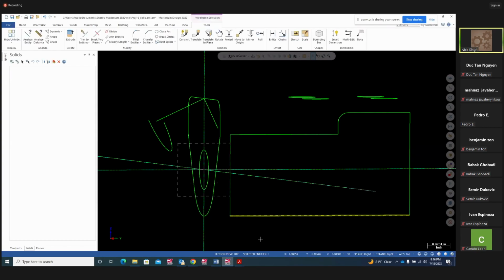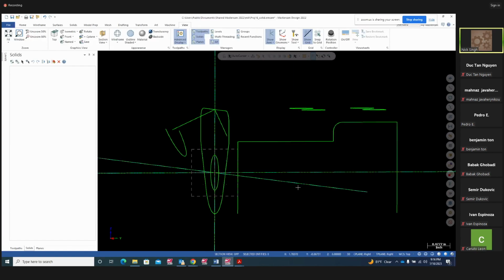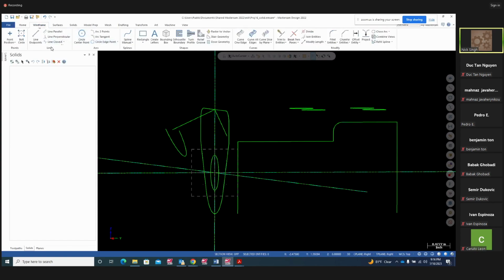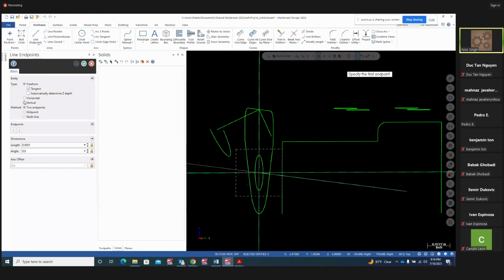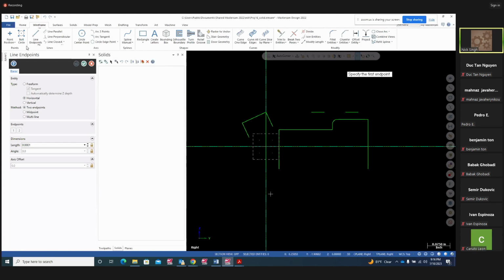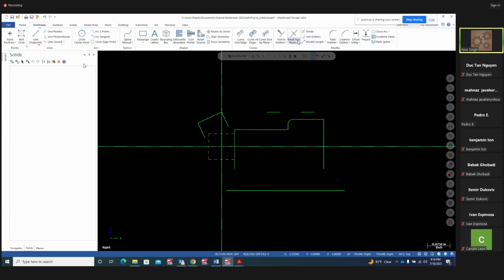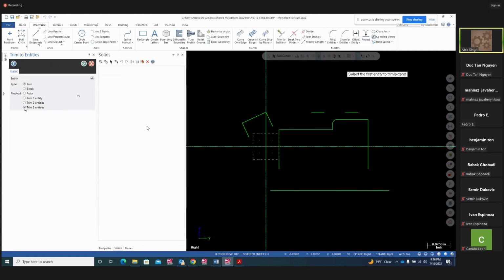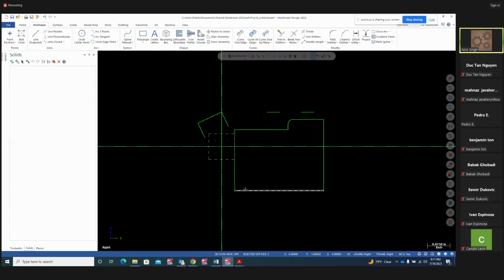geometry. No. If I'm going to delete that line, I can draw a wireframe line, horizontal, go to right plane. I can draw a line over here, that far out. And then I can go ahead and trim 3 entities. I can trim this to this, join it. So I can draw that line.